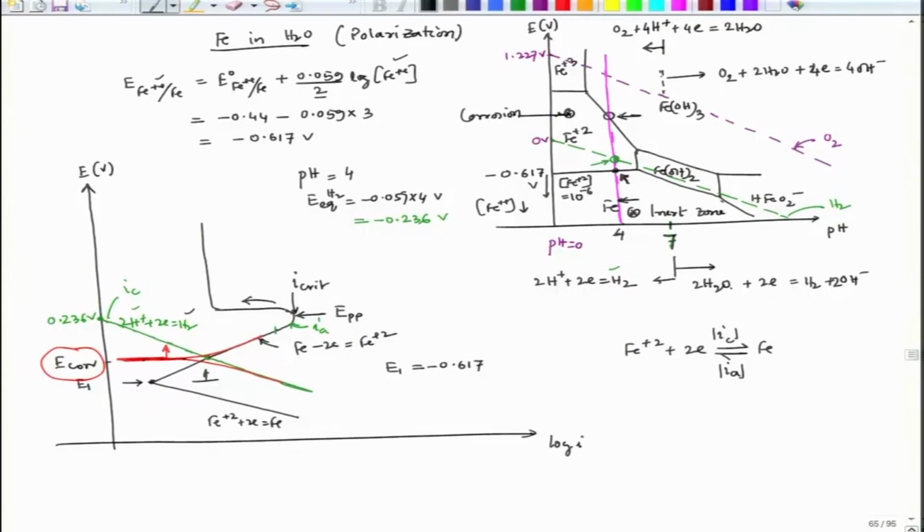and makes it passive. Once it covers the metal surface, the electrolyte is seeing Fe(OH)3 rather than Fe, and Fe(OH)3 is a hydroxide with a very low solubility product. So, that means the iron Fe3+ concentration in the solution would be extremely low. So, the dissolution would be decided by the solubility product of that Fe(OH)3.